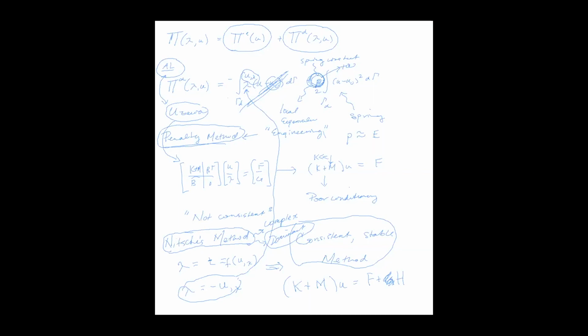So any kind of constraint enforcement. The nice thing, though, I will say about AL is, this is a very simple displacement constraint where you're just saying, I want the displacement to be equal to some value. This constraint may actually be some complicated nonlinear function of u, right? There are many kinds of constraints you may want to enforce in a general purpose finite element program.